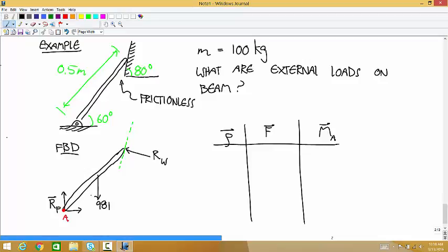And now we're just going to cycle through the forces one by one, calculate the vector going from the about point to the place where the force is applied, then put in the force vector and calculate the moment. So if this is the about point, what's the rho vector, the vector from A to the pin? Yeah, that's a 0 vector.